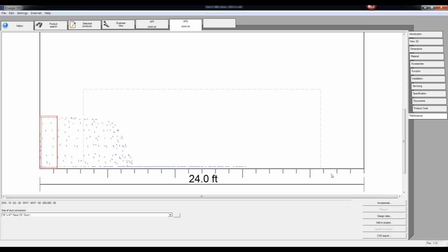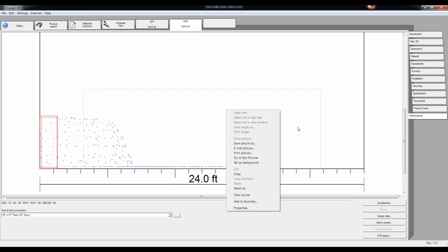That's kind of what you want it to do. In fact, if I wanted to, I could probably scale back the CFM a little bit more. But as far as whether this device is going to be able to service this room, the answer is yes, because if you remember, our rule of thumb is you can go up to about 30 feet, and this room is 24 feet wide. So this unit by itself would be perfectly fine for an office of maybe 1 or 2 people.